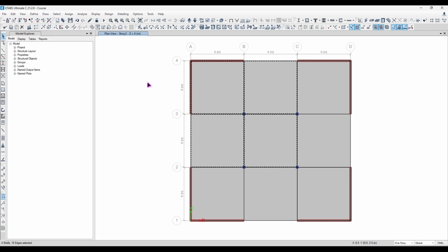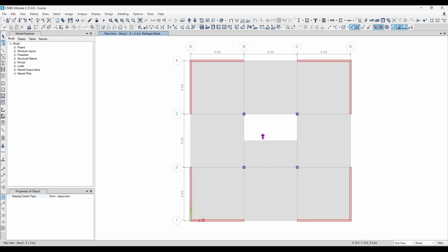Like you don't even have to select it, it's just your cursor by default. The second thing is reshape object. It's a really powerful tool, and a lot of people just miss this one. Let's say you want to decrease the size of this a little bit, just doing it quickly as a sketch, without worrying about dimensions. You can just click on it and drag it down, let's see, halfway through, and there you go.